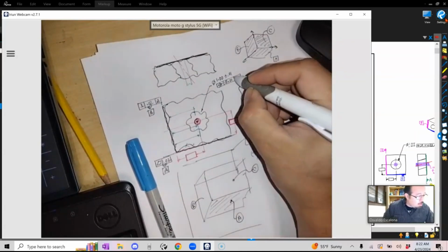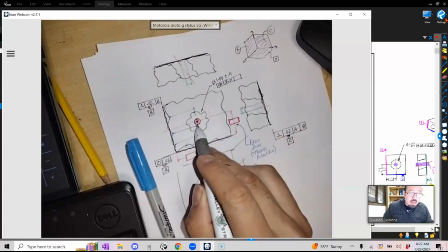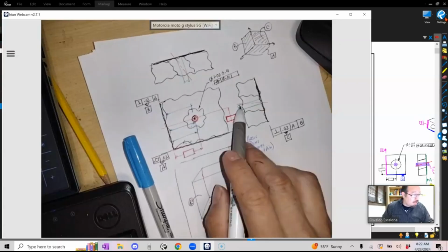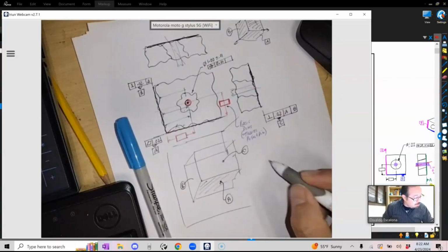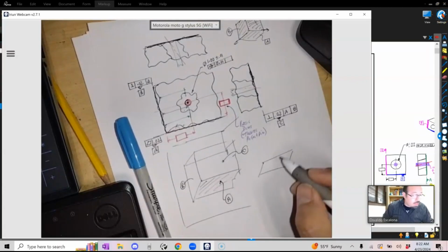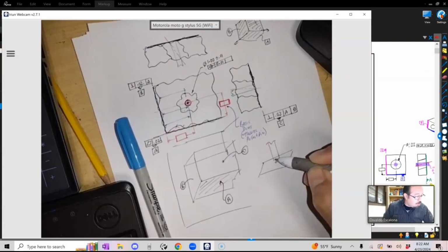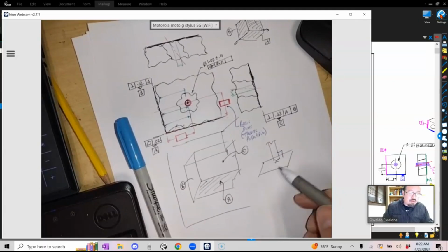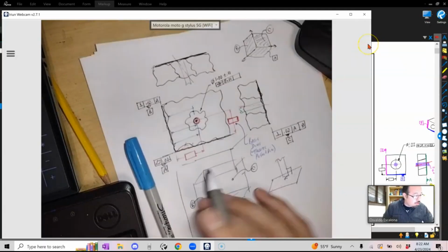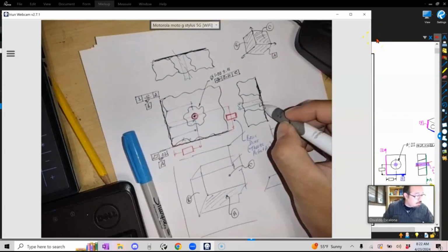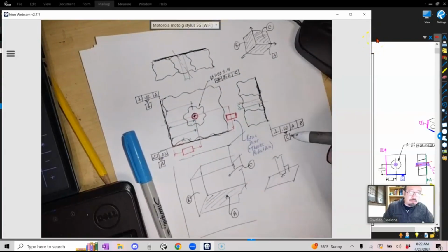And then I'm going to say that I want to locate the cylinder, and I most likely want to locate it perpendicular to a surface. So when I put the hole, I want to make sure that the hole is going to be perpendicular, right? I don't know if you guys ever try to make a hole somewhere, you grab your drill bit, and you want to make sure that it's perpendicular to the surface where you're putting the hole, right? So I want to control it. In this case, I'm going to control it perpendicular, right? So it's like that. It will be perpendicular to my datum C.